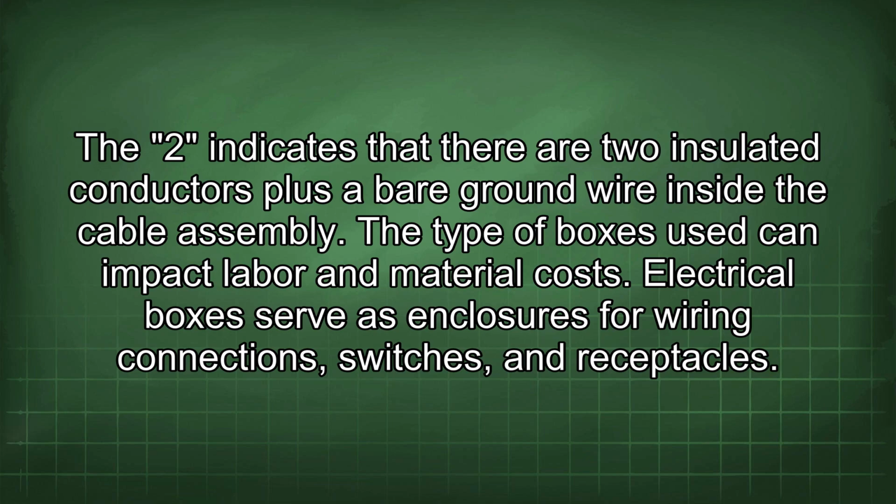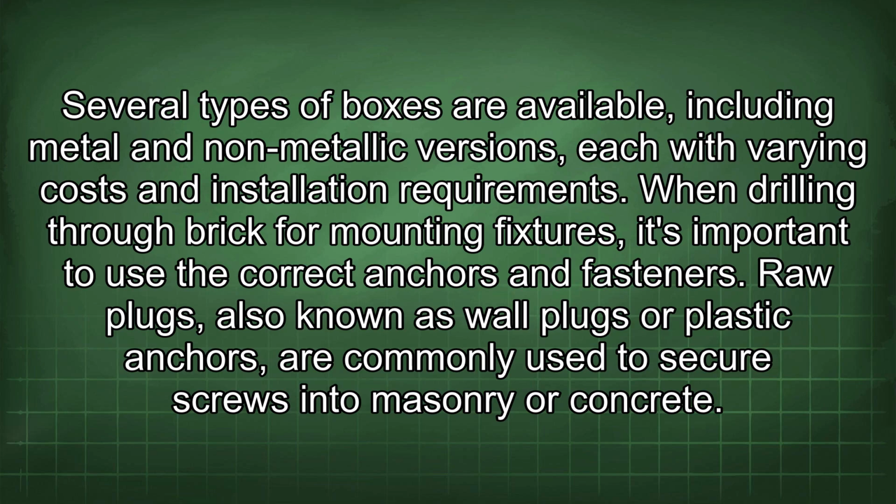The type of boxes used can impact labor and material costs. Electrical boxes serve as enclosures for wiring connections, switches, and receptacles. Several types of boxes are available, including metal and non-metallic versions, each with varying costs and installation requirements.